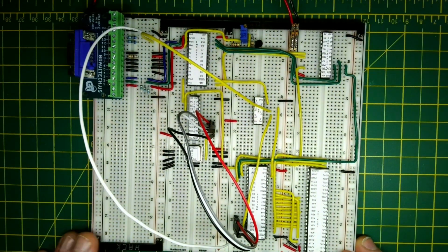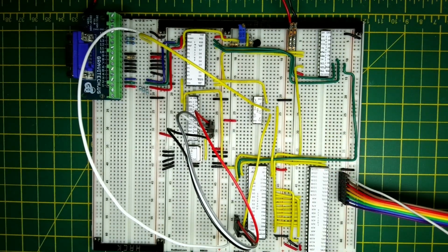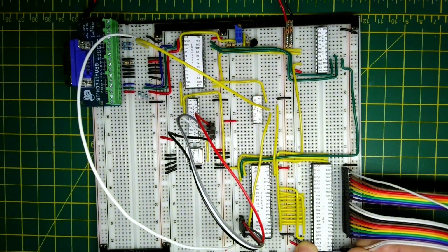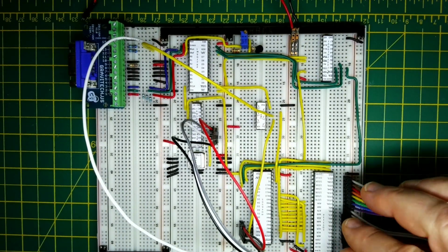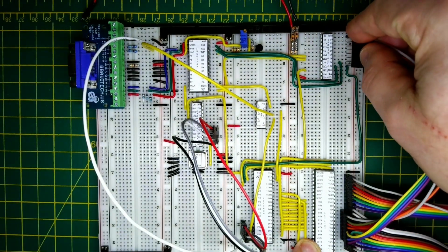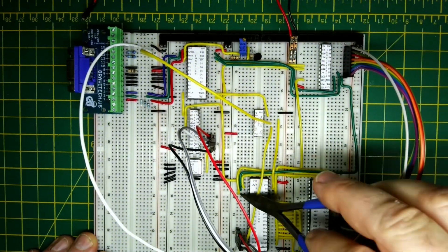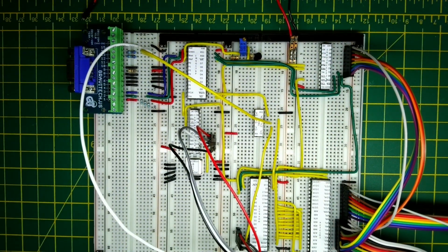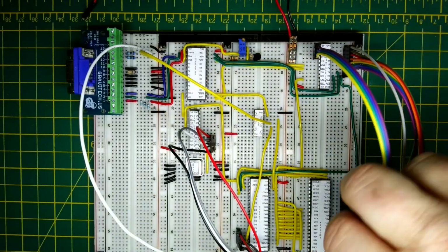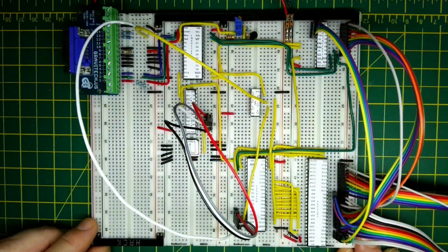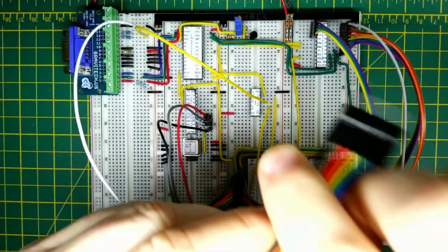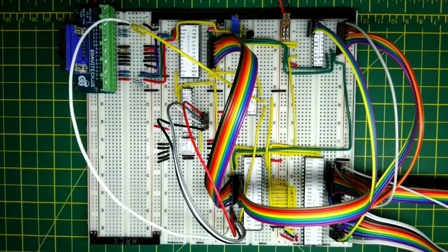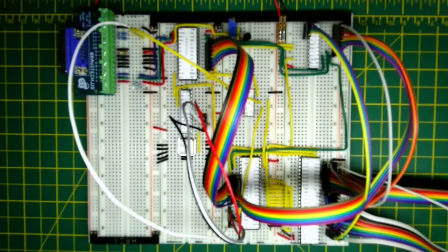Put in a power distribution bar. Now we're going to wire in the data lines to the main processor board and the address lines. Then we're going to take the address lines up to the IO decoder. That's the A0 to A7 and then the top address lines as well. And now we're going to need to wire in the data lines to the CRTC and also to the video DAC. Just check those as well.